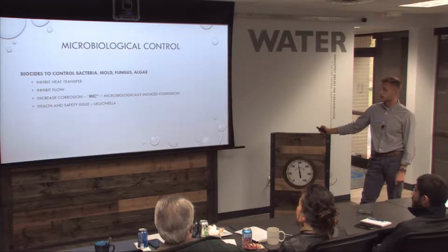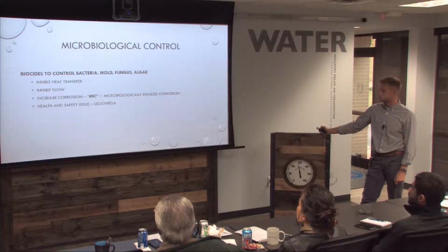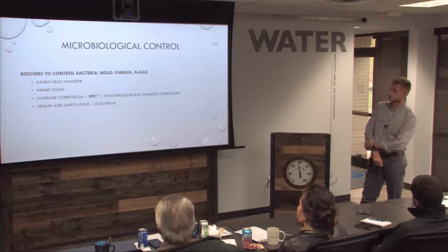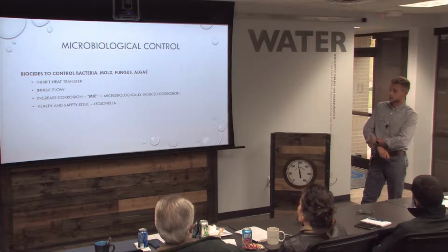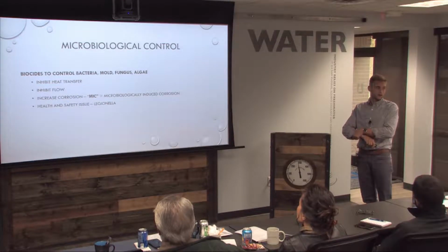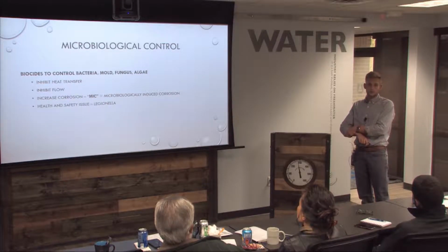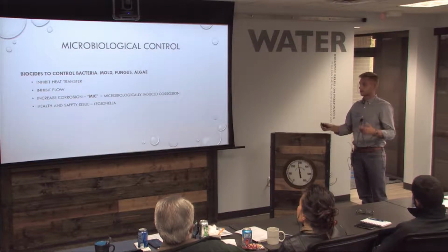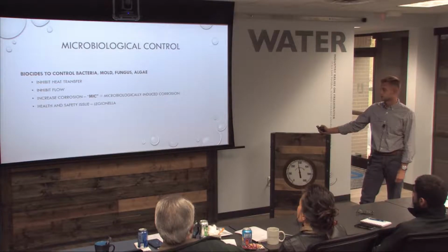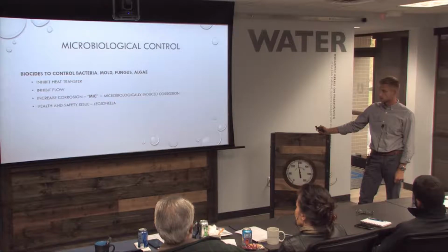Major problem, not only from a heat transfer and flow inhibition, but corrosion. So microbiologically induced corrosion is a big deal. And not only that, a health and safety issue. I don't think any healthcare facilities are present today. Either way, I think it's making its way towards commercial office buildings, but looking out for Legionella is going to be extremely important.